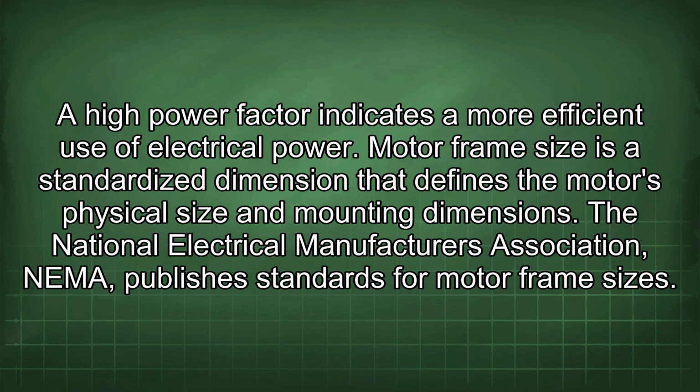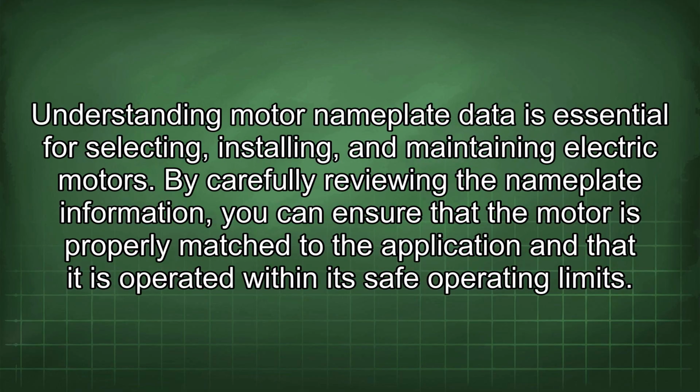Motor frame size is a standardized dimension that defines the motor's physical size and mounting dimensions. The National Electrical Manufacturers Association (NEMA) publishes standards for motor frame sizes. Understanding motor nameplate data is essential for selecting, installing, and maintaining electric motors. By carefully reviewing the nameplate information, you can ensure that the motor is properly matched to the application and that it is operated within its safe operating limits.